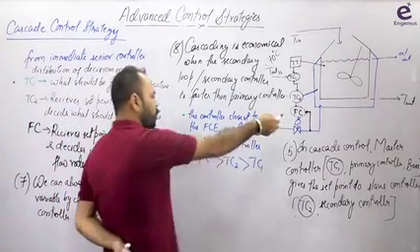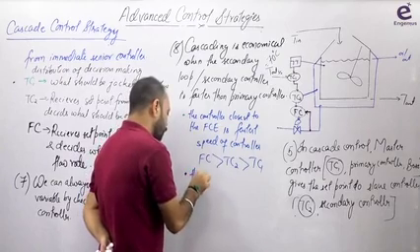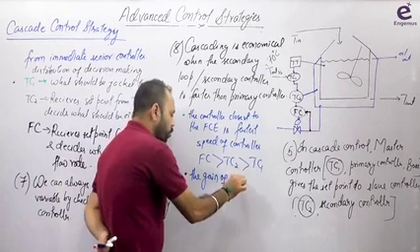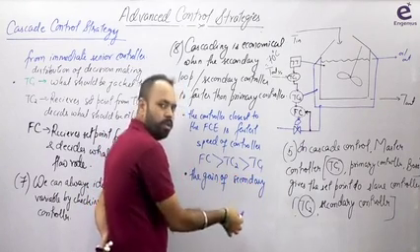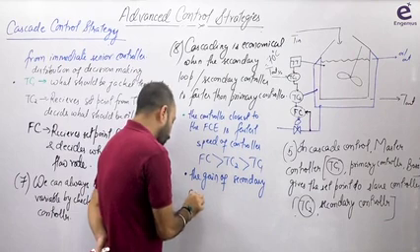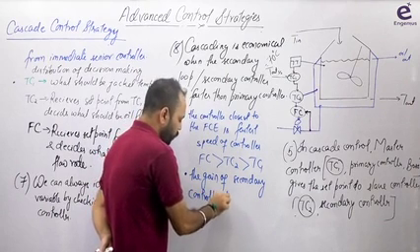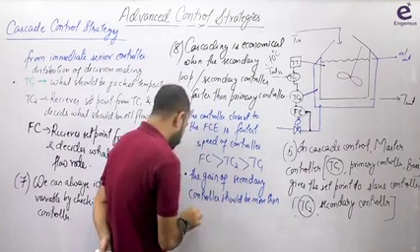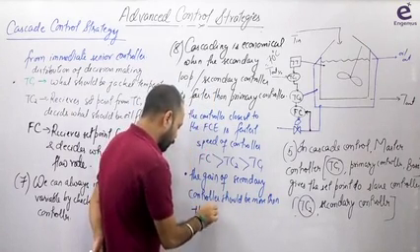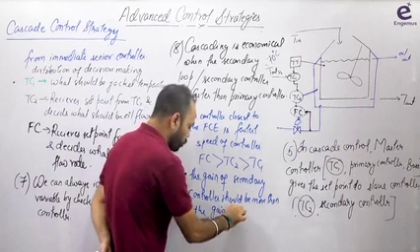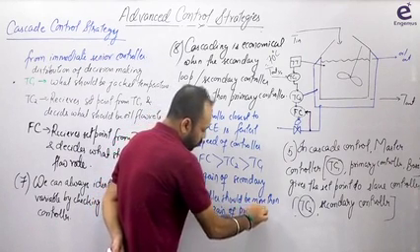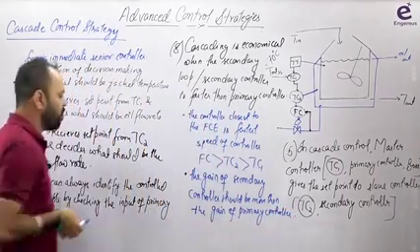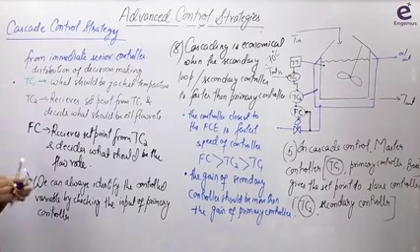Okay, I can also say that if this controller is fast, there's one more point: the gain, KC, the gain of the secondary controller should be more than the gain of the primary controller for cascading to be economical. This is point number 8: the gain of the secondary controller should be more than the gain of the primary controller. Are you understanding? This is how cascading works. Primary controller, okay, note it down. Okay, this is the 8th point.